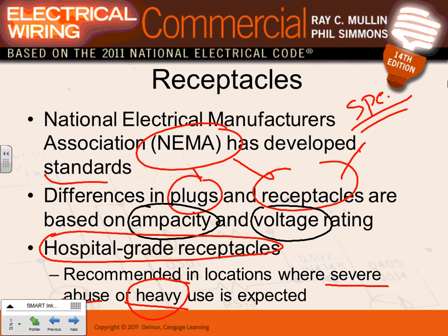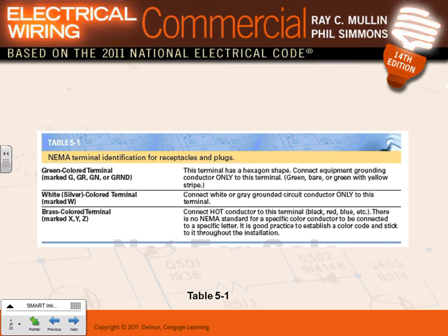The spec receptacle and switches versus non-spec. So, when it comes to a commercial industrial building, moving on right now, you're going to forget the residential grade receptacle. These cheap little ones, 33 cents or $1.30 for the tamper resistant. We're going to forget about them. We don't install them. Can we install them, by the way? Can we install these in a commercial building? Yes, the code doesn't care. A good engineered project will eliminate them.